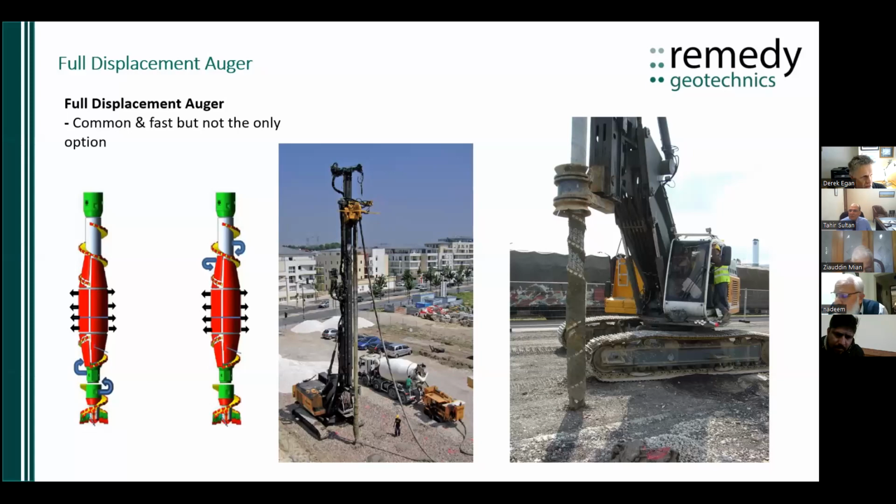I think you would typically use finite element programs to do the design, and I shall show some finite element output in a minute. And indeed, yes, you do get stress concentration at the head of the column. The load increases from the head to the neutral axis within the column, and then diminishes below the neutral axis, and we'll see that in a minute.